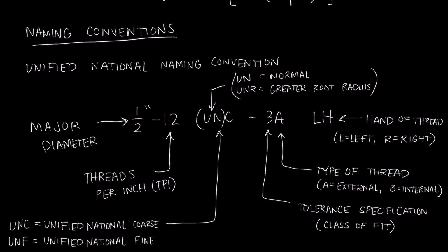And also on this note, while we're talking about different applications. So for the UNC, UNF, UNEF bolts, keep in mind that the UNC bolts are going to be good for general assembly, and if you have to do frequent disassembly, right? Because if I have a coarse thread, it's not going to take me as many turns of the bolt or of the nut to get a joint tightened. Whereas if I have a fine thread, then I'm going to have to rotate the bolt more times just to get that same axial movement of the bolt or the nut.